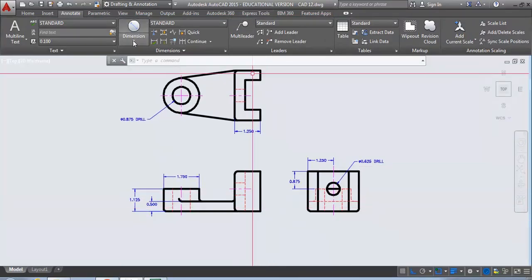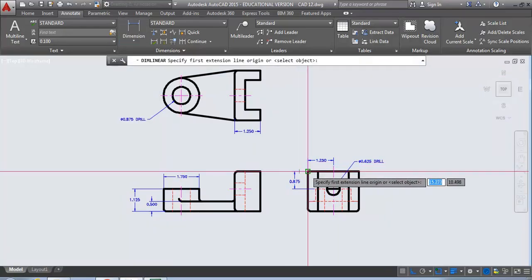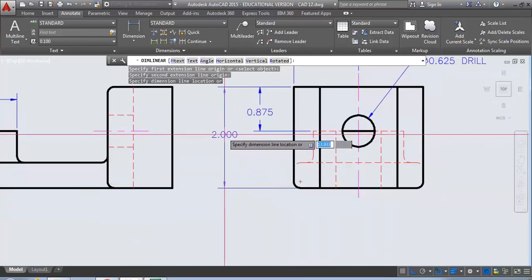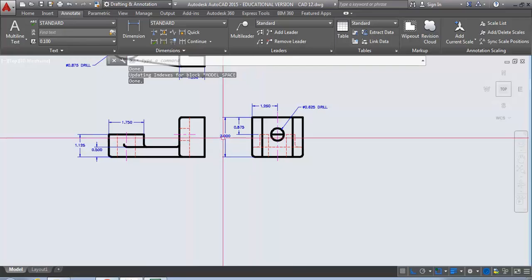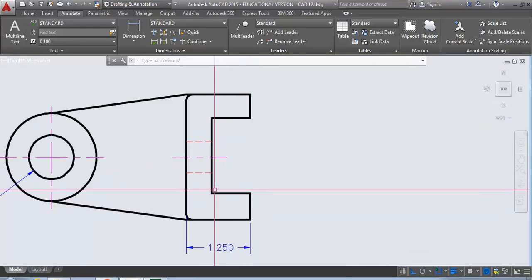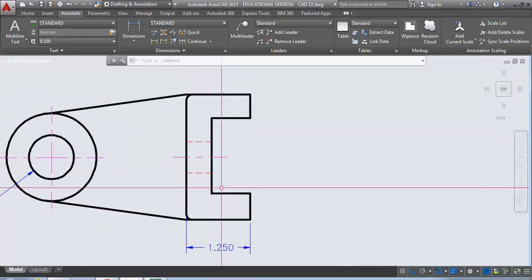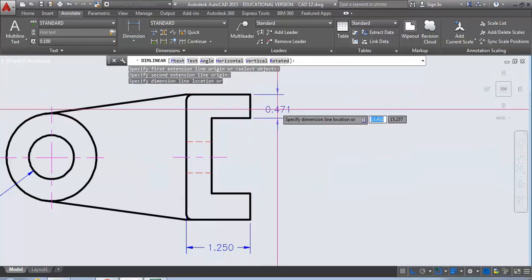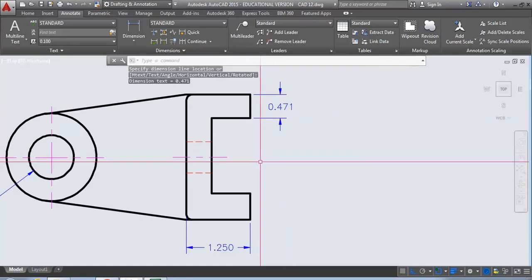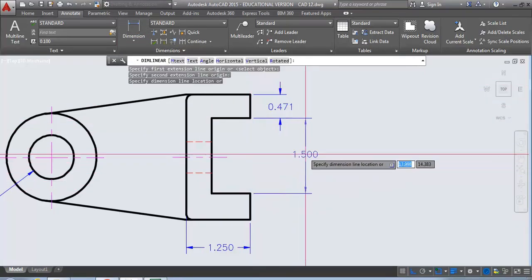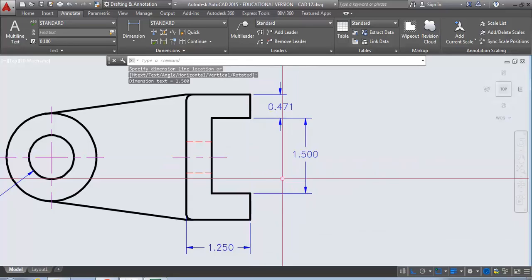Let's put our 2-inch. So it looks like from here to the bottom is 2-inch. See, I keep the dimensions in between the views when all possible. And since this is the contour here, I'm going to use that as the dimensioning dimension there, because it shows me the contour. So that's not right. That should be a 1/2 inch. See? And then this should be 1.5 inches. It's alright, I'll show you how to change them. I'm glad there's mistakes. And it should be 2.5 that way.